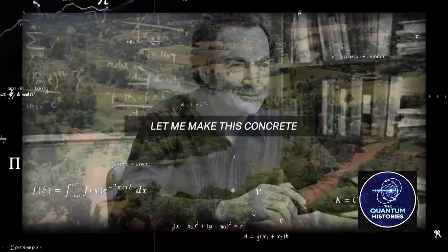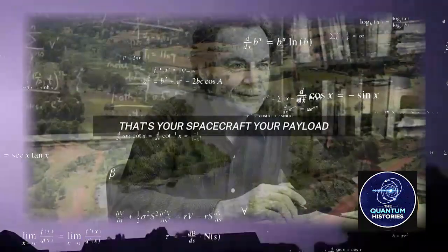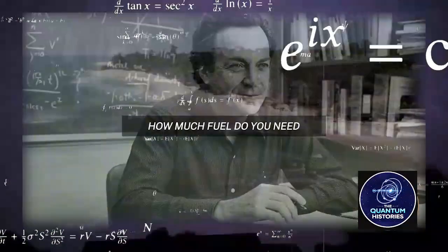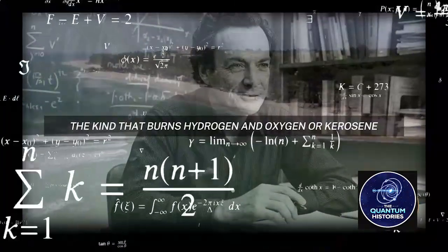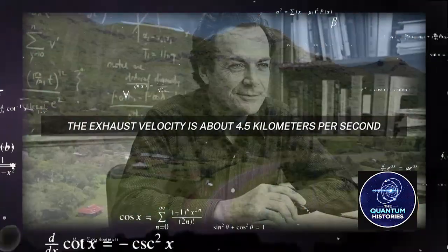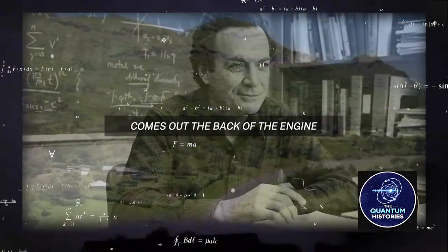Let me make this concrete. Say you've got a rocket that weighs 1 ton. That's your spacecraft, your payload, everything. And you fill it with fuel. How much fuel do you need? Well, in a typical chemical rocket, the kind that burns hydrogen and oxygen or kerosene, the exhaust velocity is about 4.5 kilometers per second. That's the speed at which the burning fuel comes out the back of the engine.